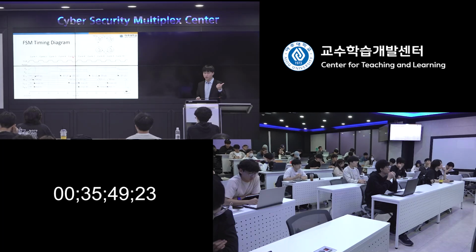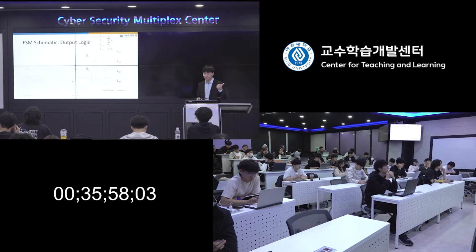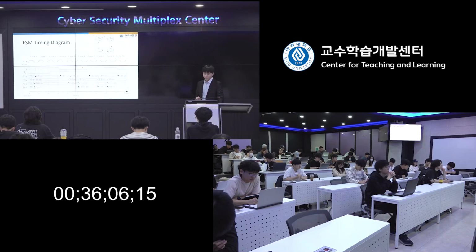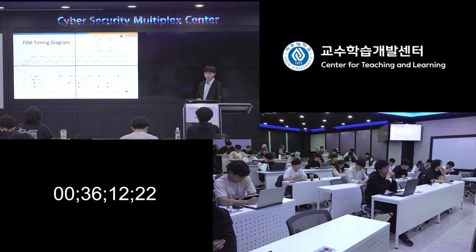When we reach cycle number 5, there's a rising edge. This S1 will be outputted by this state register, right? From S1 to S prime to S. Now, since the current state is S1, it will immediately affect the output.